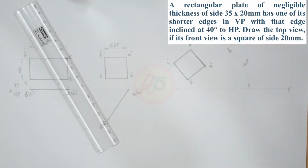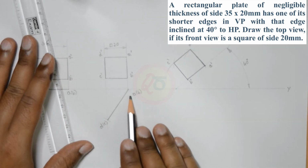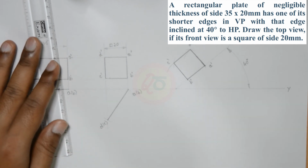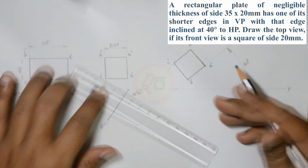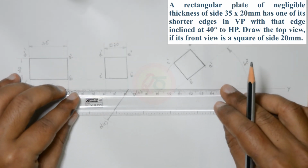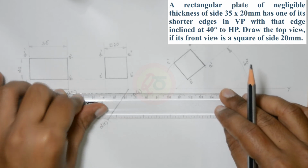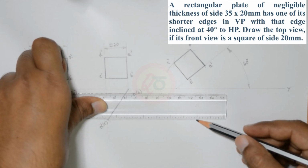Okay. Fine. Now we need to draw the projections from A dash, B dash, C dash, D dash, and intersect them with the projection lines from AB and DC of the second position top view to obtain the final projected view, which is the top view. So from C dash, or C and D of the second position, let me draw a projection line with a 2H pencil.